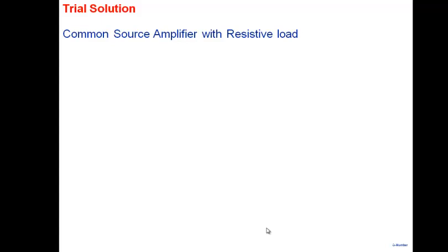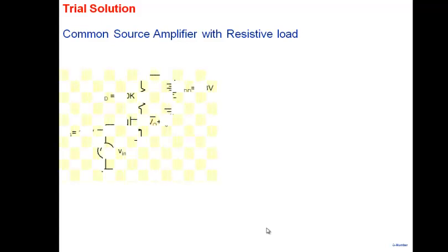Anyway, so let's start. As I said, the first amplifier that we take is a simple common source amplifier with a resistive load here. Resistive biasing, and you can make it using a P channel as well. So in this case, we have an N-channel MOSFET here. This VG is used to bias this particular MOSFET in saturation region or above threshold. And VDD supply voltage, as I said, for us is plus 3.3 and minus 3.3. This is a single supply amplifier, so we have used only one supply voltage. We could have also put here minus 3.3 as well, so that would be a dual supply-based amplifier.